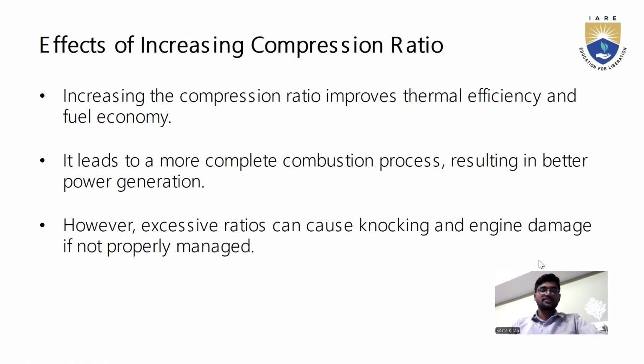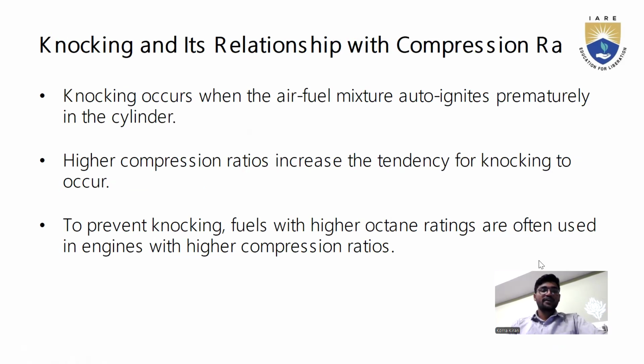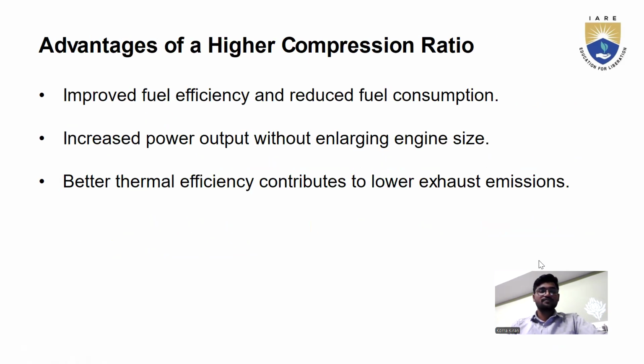The effect of increasing the compression ratio is improved thermal efficiency and fuel economy, and it affects the combustion process. Knocking has a relationship with the compression ratio: knocking occurs in the air-fuel mixture, and to prevent it, fuel with a high octane rating is often used with higher compression ratios.